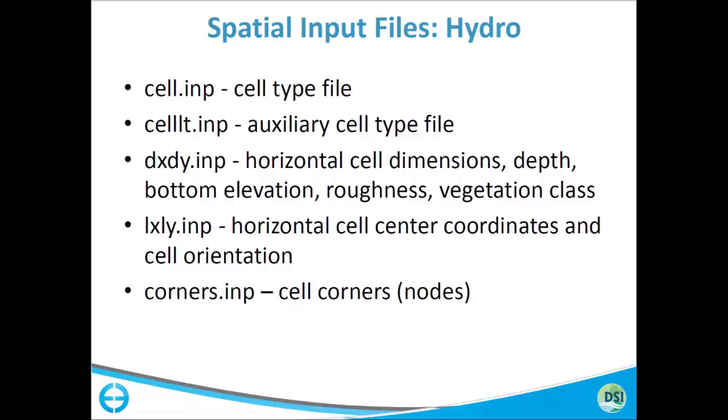But EFDC doesn't care what the actual cell centroid coordinate is. EFDC does not use that value anywhere unless you're simulating wind shear processes. EFDC knows that cell A is next to cell B because of the cell map. So it maps a particular I and J into a certain set of dimensions, and then it only cares about I plus 1, I minus 1, J plus 1, or J minus 1, etc.